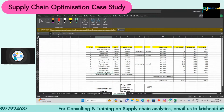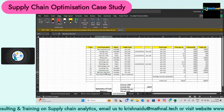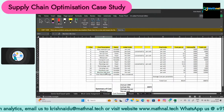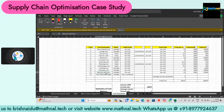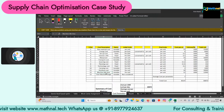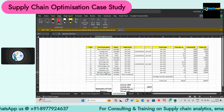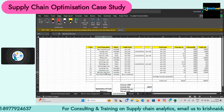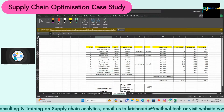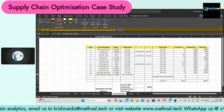Then your machine idle time. Suppose your machine is there, but it's not actually running. Even though the plan was there to manufacture, we are not able to run the machine, so that is idle time. Suppose the production is not scheduled and the machine is idle; we may not include that idle time as one of the cost parameters. But if the production is scheduled but we are not running the machine, in that case we are going to have machine idle time. Okay. Then the last one is the over machine usage, right? If you're producing extra products, extra volume, more than the required one, that is the over machine usage.